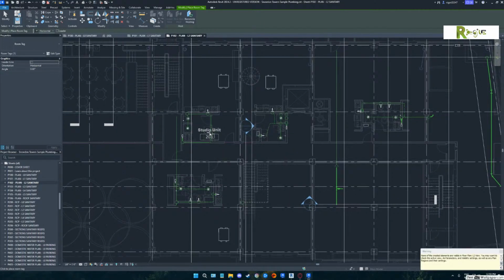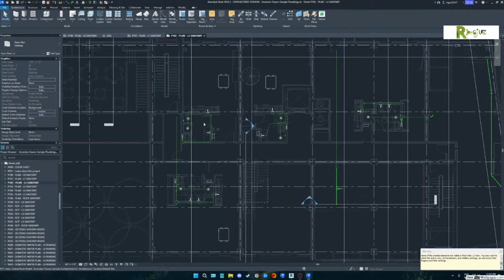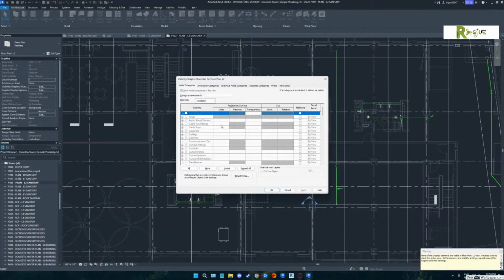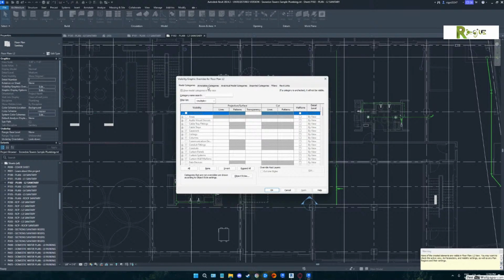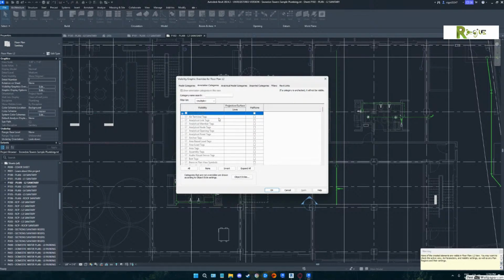All right, it put it in there, but they're not turned on. So hit escape. I want you to do a VV. Okay, and I want you to go to the annotation tab on the top of the screen, and turn on your room tags. You're right, there's a checkbox at the top that says show. Nope. Look, room tags are turned on. That's not what's getting them, though.